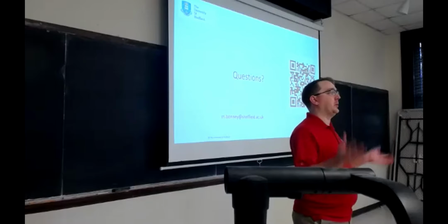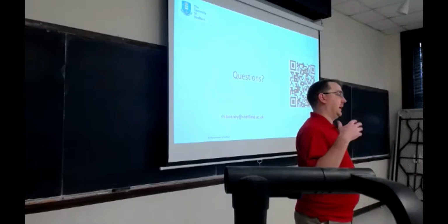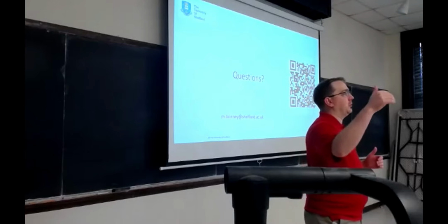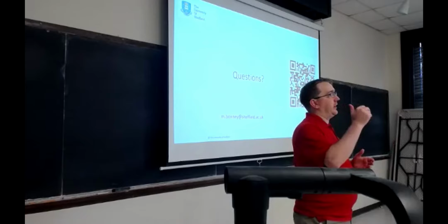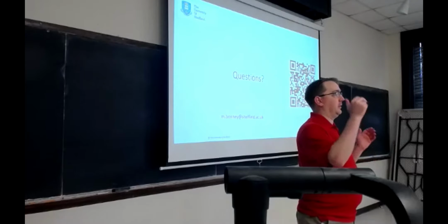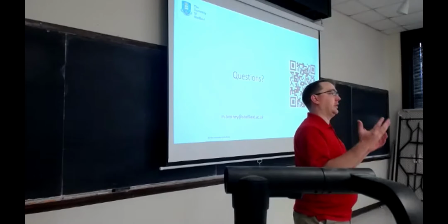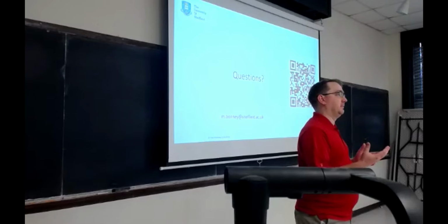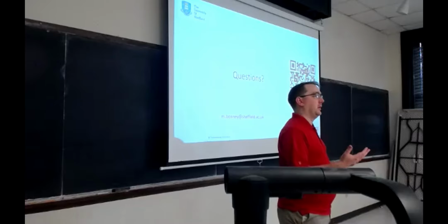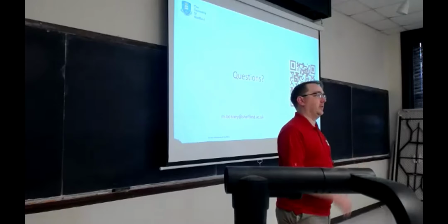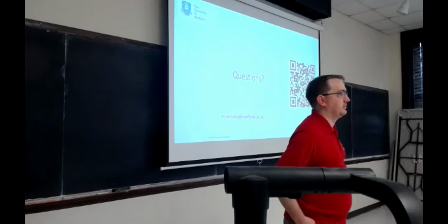So visualizing something like the executable digital twin from Siemens, that uses surrogate modeling. It does full finite element analysis and creates reduced order models based on input location. And it creates a set of these. So when it sees this particular point as being excited, it goes to that reduced order model and actually calculates what the rest of the system is going to be. So that uses the full finite element model to inform the surrogate model that uses real-time analysis. So that's an example of it.